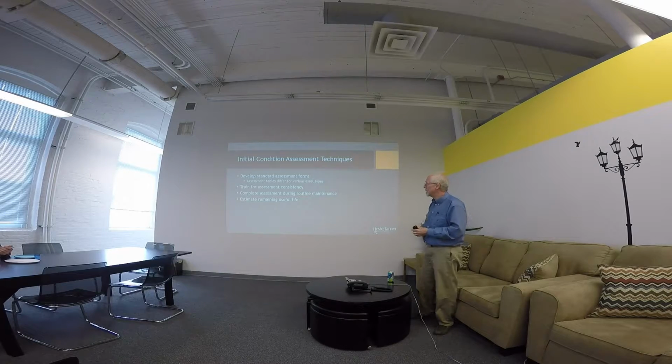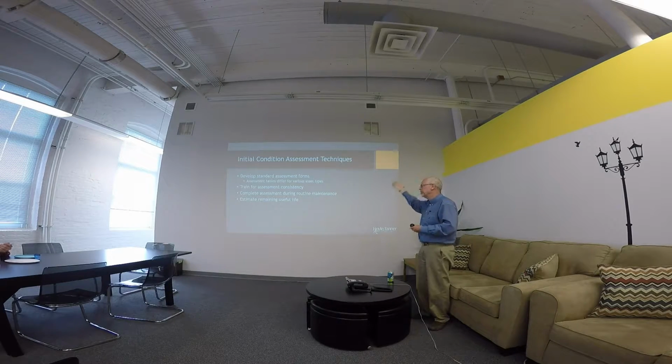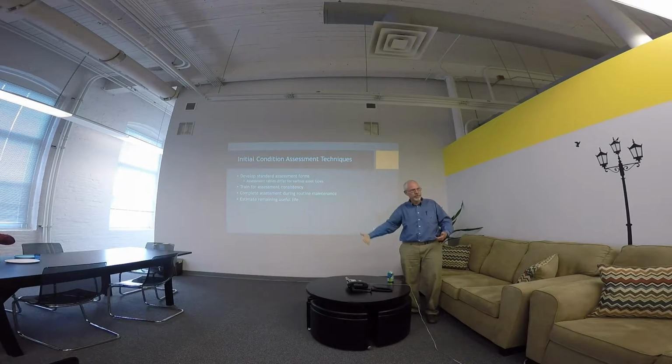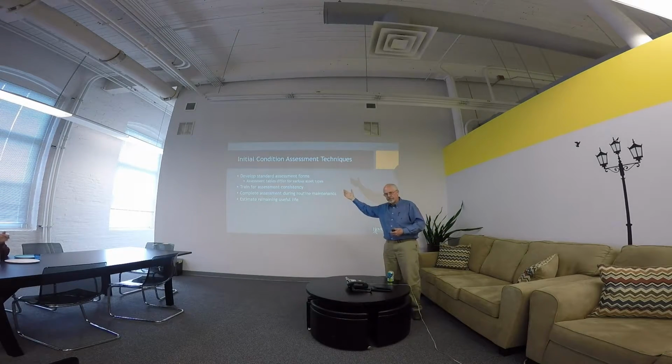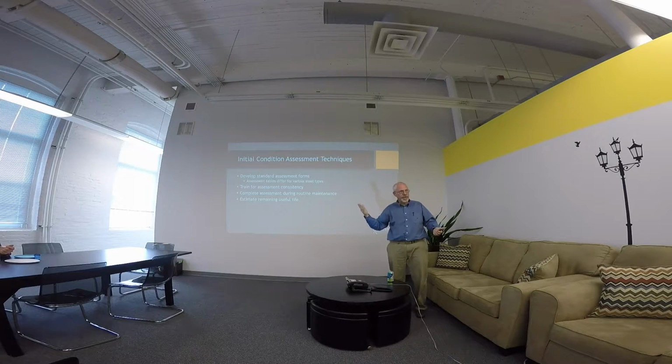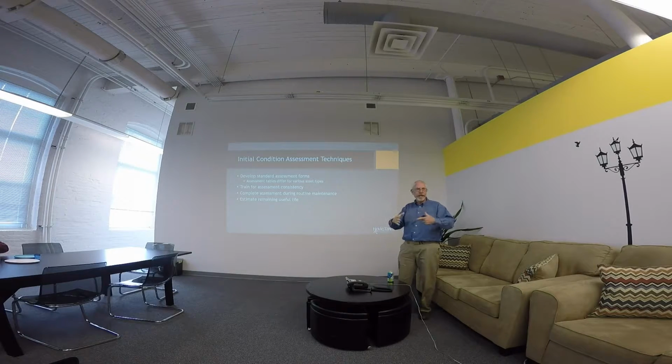Okay. Developing the standards. Enforcement. Basically, the standard would be that table. So enforcement, for part of our workshop, we set up several tables for different types of assets. We did fire hydrants, and we said, okay, what are the things that break on the fire hydrant? The threads, the cap, the bonnet, the stem, leakage, the breakaway. So we go through and we write down all the different levels. How do you inspect it? How do you develop that standard?